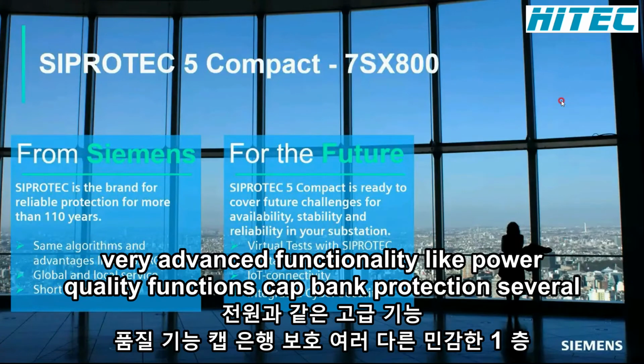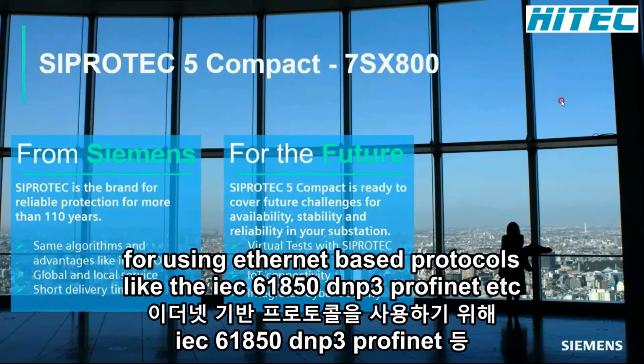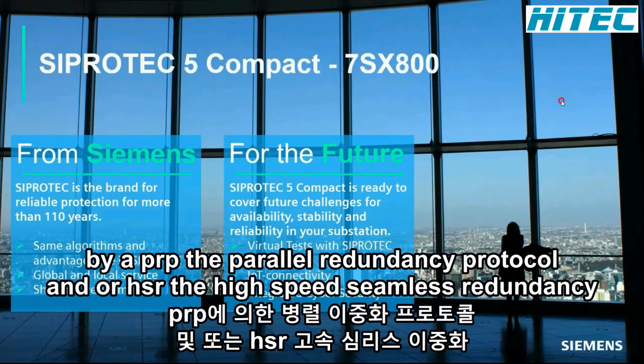We have advanced functionality like power quality functions, cap bank protection, several different sensitive ground fault protection functions, and the redundant Ethernet interface for using Ethernet-based protocols like the IEC 61850, DNP3, Profinet, etc. And all in all, together with the high available station communication via PRP, the parallel redundancy protocol, and or HSR, the high-speed seamless redundancy.